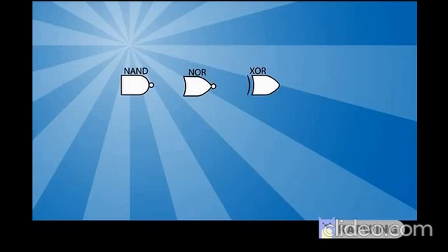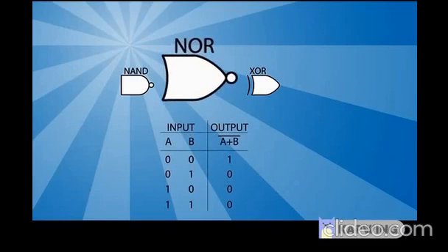So what NOR gate does, and you can see the symbol is also very similar, like an OR gate with a bubble. The bubble is from the NOT gate, right? And the output is A plus B, with a bar on the top. So whatever is the output of the OR gate, it makes it reverse, because then it is passed through a NOT gate.